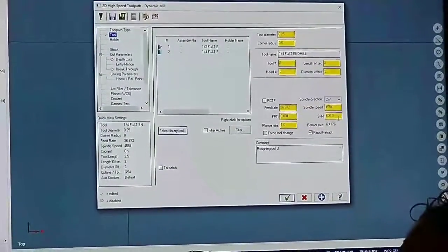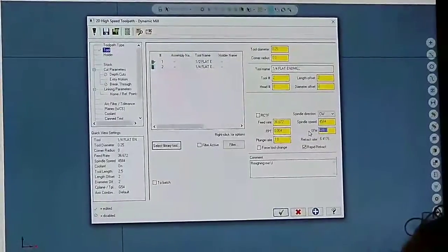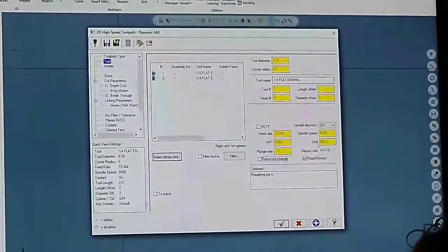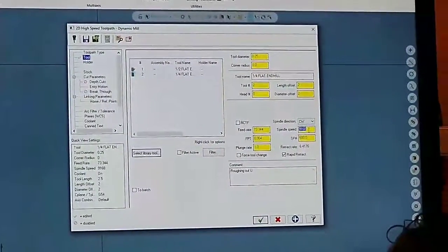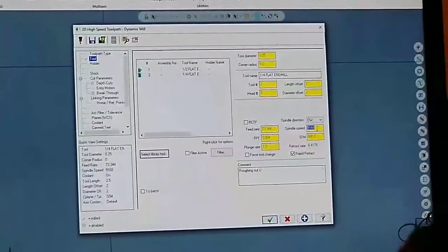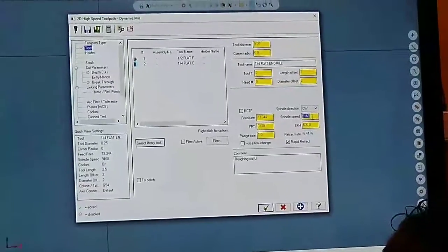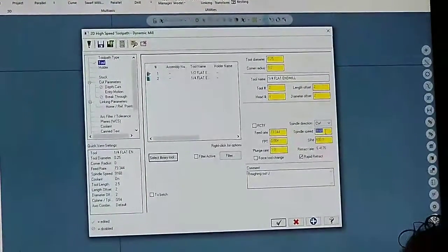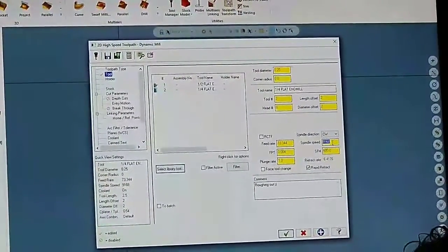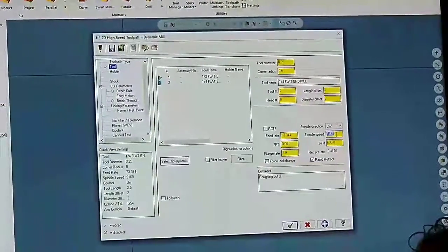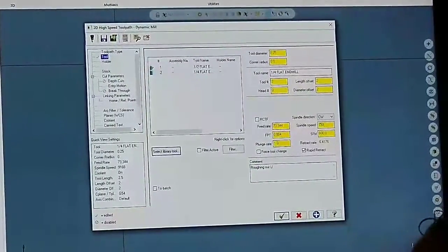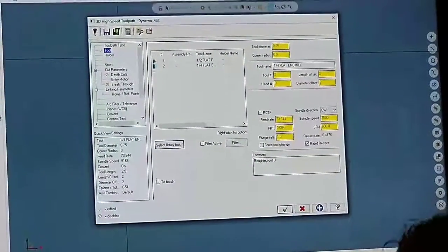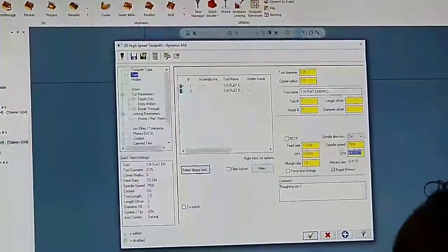Now I'm going to set my speeds and feeds for this one, so same thing. I'm going to go 600, and when I hit tab, it'll automatically calculate my spindle speed. Well, look what it did. Put my spindle speed at 9,000. How fast does my machine go? About 7 maybe, 8,000. But it's scary to run right at the top, so I'm just going to hard data change this. I'm going to go spindle speed, 7,500 RPM is the fastest I'm going to go, just because I don't like to run right at 8,000. All right, so I got 7,500 here.